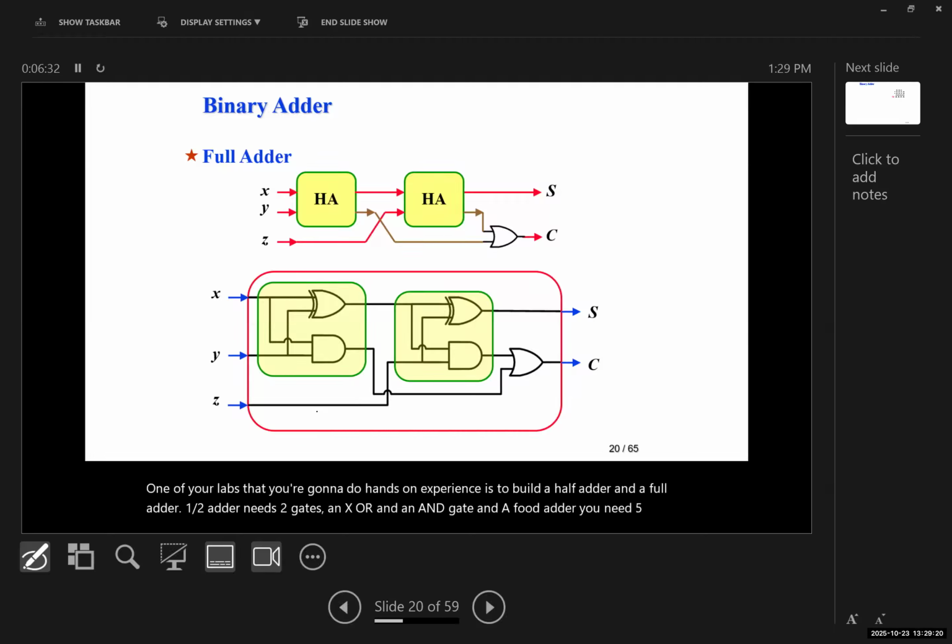For example, here, if A is 1101 and B is equal to 0111, then A is greater than B. So this output would be 1 and the rest of them would be 0. Okay. This is expandable to more numbers of bits, so you can have 8, 16, and so on. Now here, we're going to have 4, obviously.